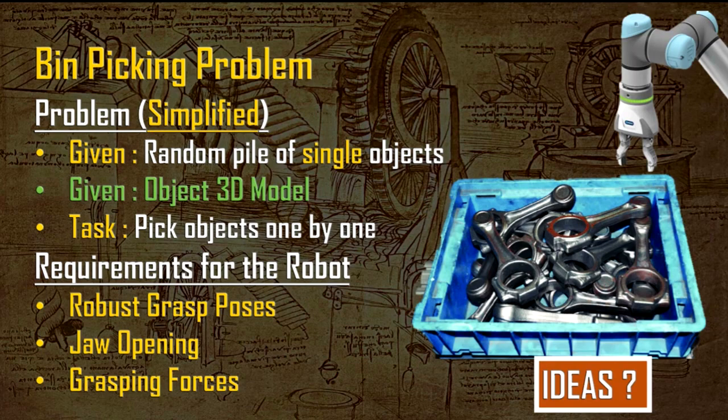This is how it works. You will have a fixed camera location in your cell, and you would have already fed the camera location into the robotic system. There will be a transformation from the end effector to the camera, and from the camera to the identified object.